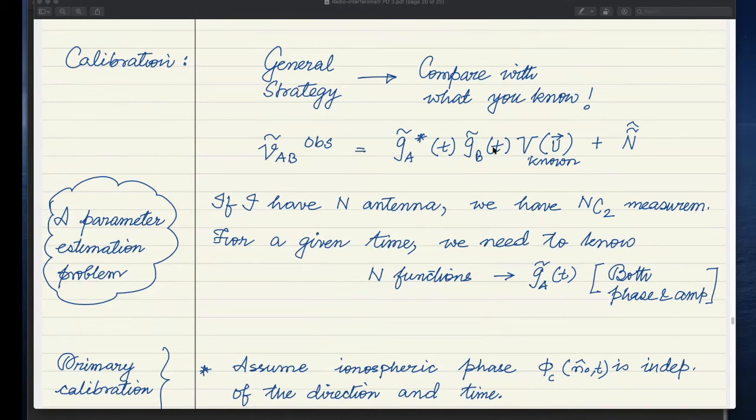You may choose to divide it into, say, 1 minute, or you can also integrate over the entire 2 minutes to get a better signal to noise. As you know, if you integrate for longer time, then the noise decreases. Remember that this is not all. You have a noise part also sitting over here. That will decrease if you integrate over longer time, but longer time within the observation of that calibrator source.